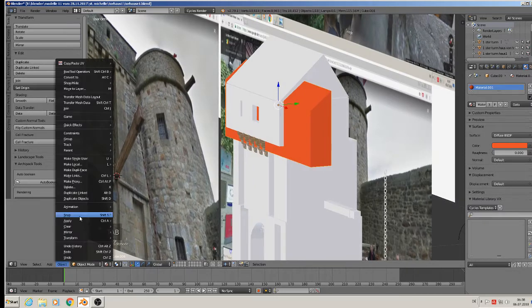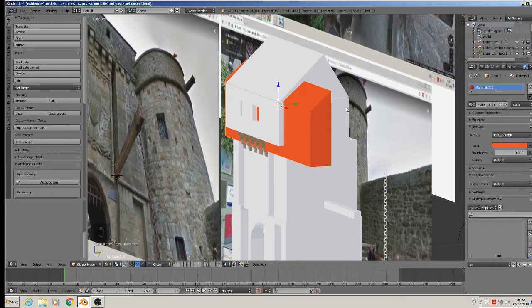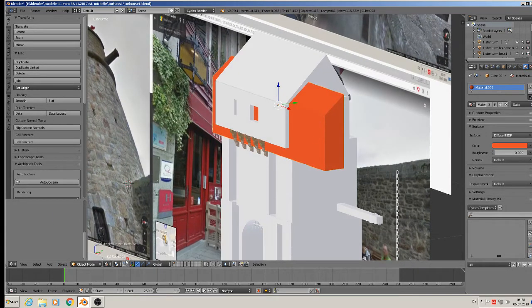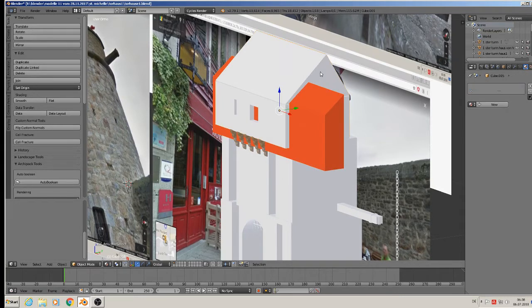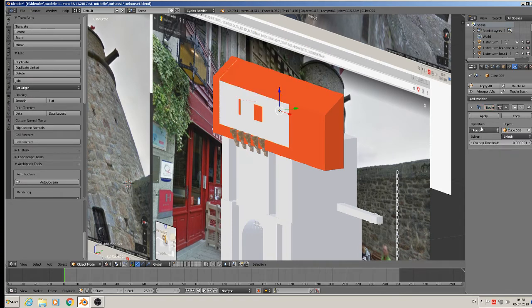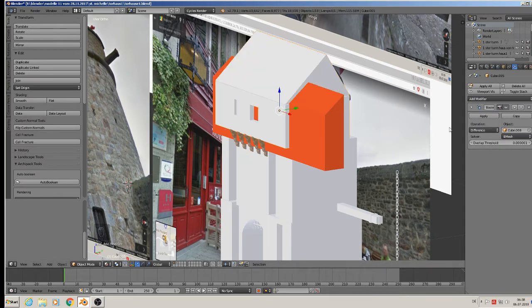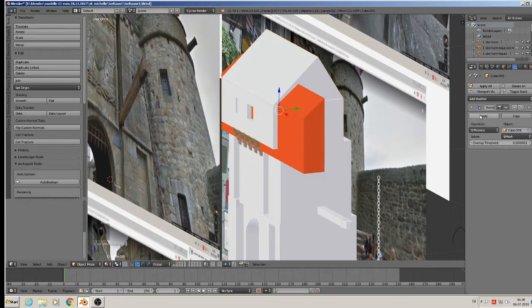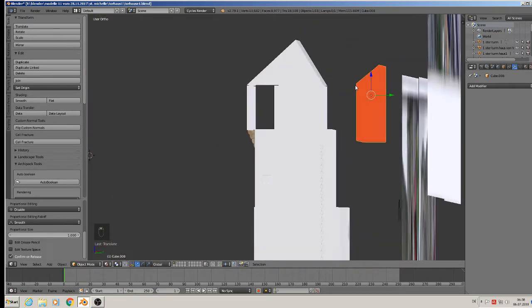Then we must surely apply the rotation and scale again. The name of the red object is Cube08. So we can take the Boolean, and Cube08, in Difference. So apply, and we can bring that out.